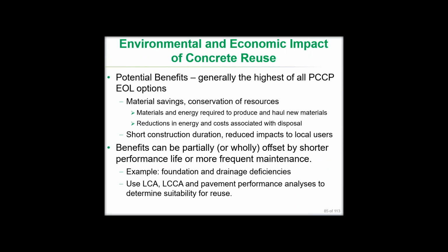We're eliminating the energy and the costs that are associated with disposal. And we usually have a relatively short construction window. If the existing pavement is in place, you're not rebuilding subbase, you're not doing drainage, you're basically just overlaying or building on top of that. It becomes a much shorter construction duration, often lower cost, lower societal impact. So generally a very, very highly desirable end-of-life option if it can be accomplished.